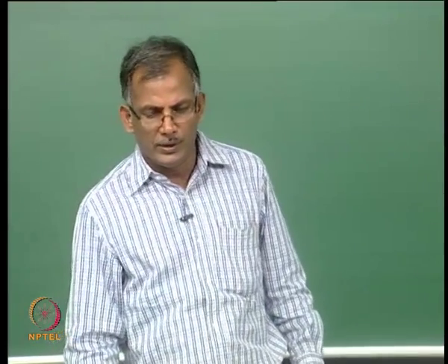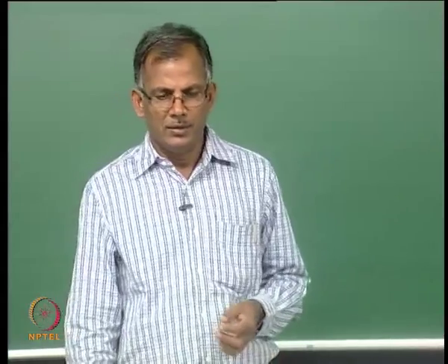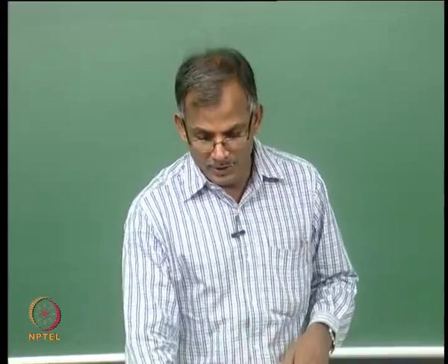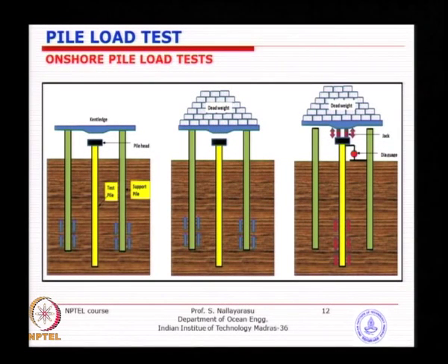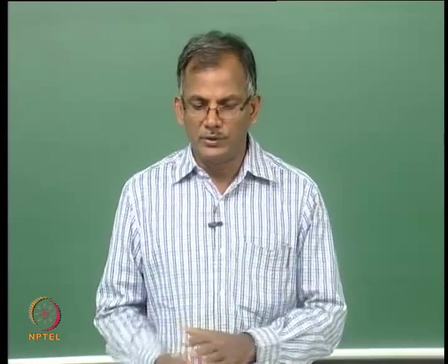Let us continue with the pile testing. By this I think you could understand the three concepts. Concept 1: foundation by means of simple spread footing for the Kentledge itself, and basically piled foundation where the ground condition does not permit load distribution around the test pile. The primary concern is we should not put undue load to the pile soil interface which is being tested.